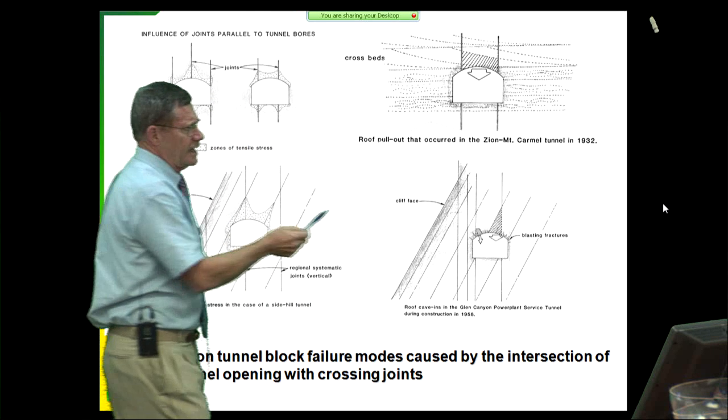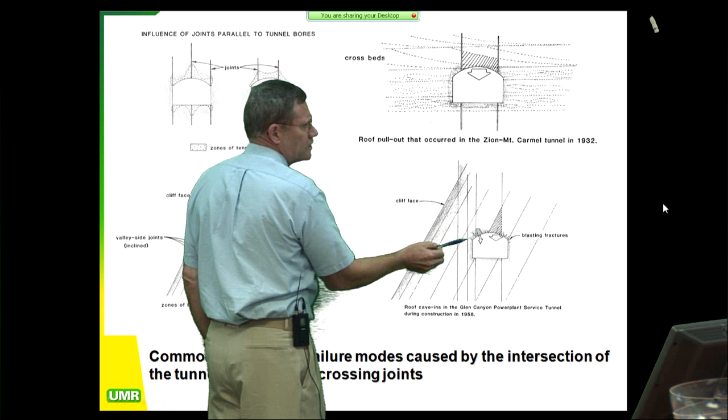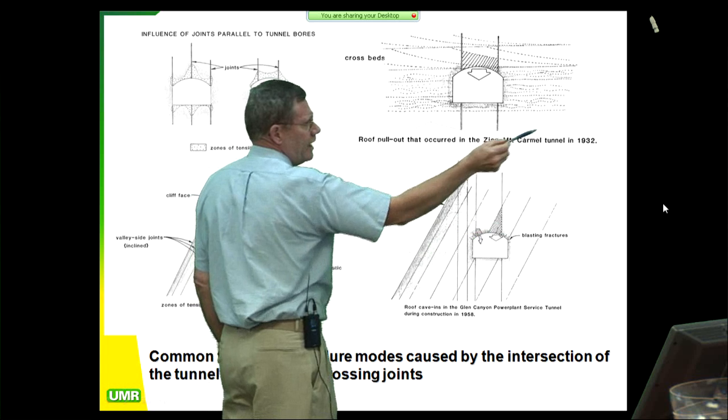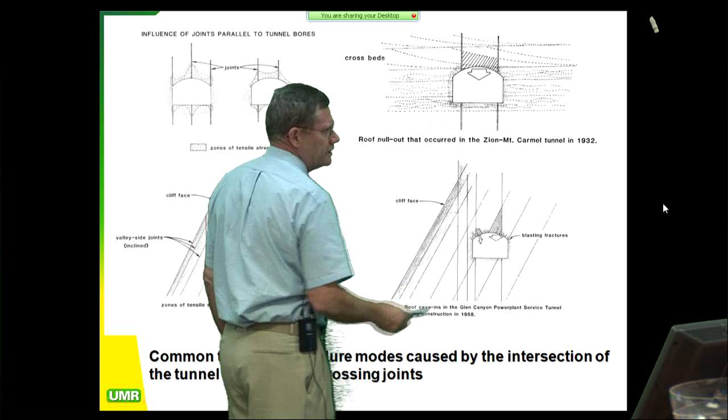So this is the kind of case where you're going to have a shield of some sort or spiling reinforcement, which are rock bolts you shoot out in front of the tunnel heading to try and pin these things.